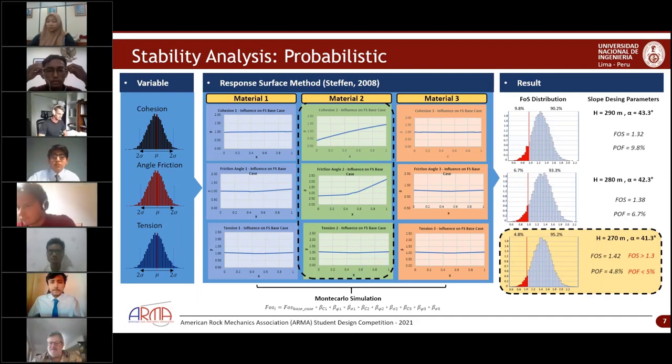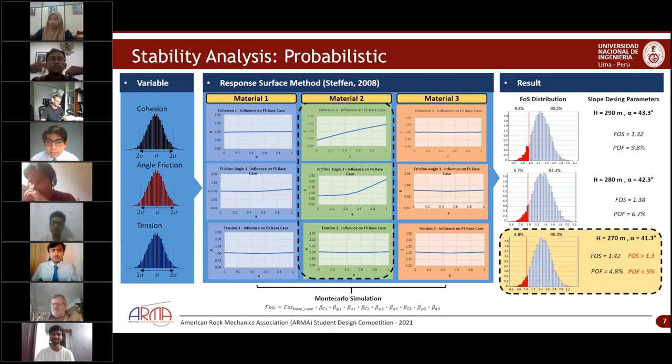I have a question, if I may. One of your risks was that the water would be present at all times, and yet your analysis shows it present at all times. So I'm wondering, you've taken the very, very worst case. Did you consider lowering the water table through pumping at a cost and creating a water table that was not at the surface of the current pit?